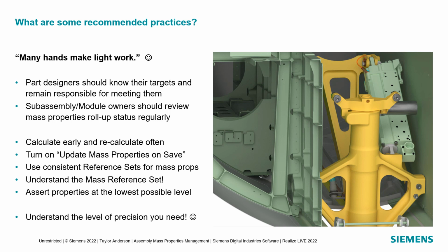I recommend that you automate everything you can here. There are a bunch of things we give you there. I encourage you to check out the customer default options carefully and to set those site-wide as needed. That's very, very useful to look at, and we're happy to talk with you about some best practices specifically there. One of these is the model reference set, or the mass reference set. This is the model reference set by default. NX likes the model reference set by default if you can stick to it.